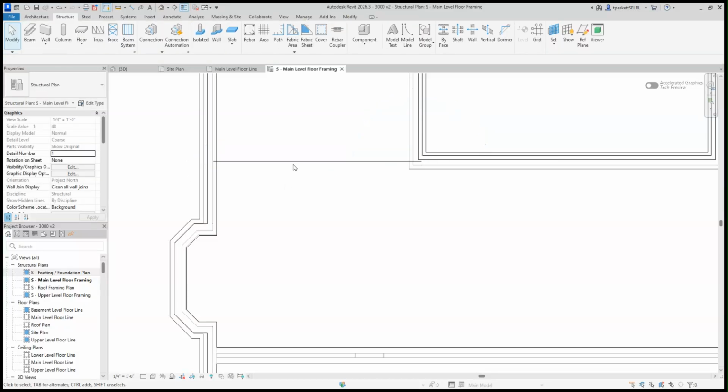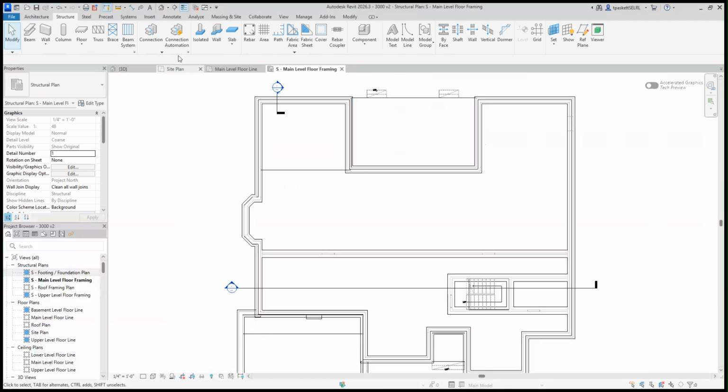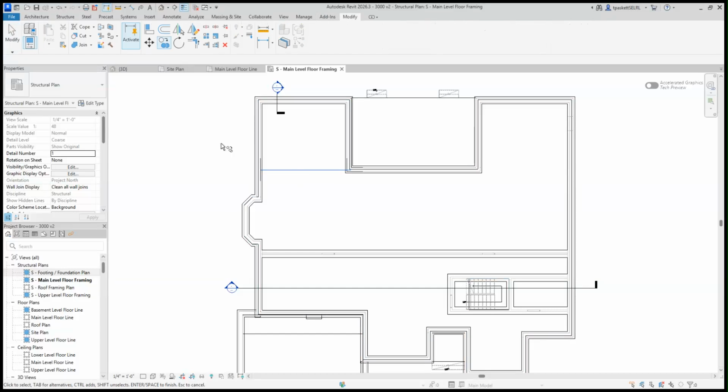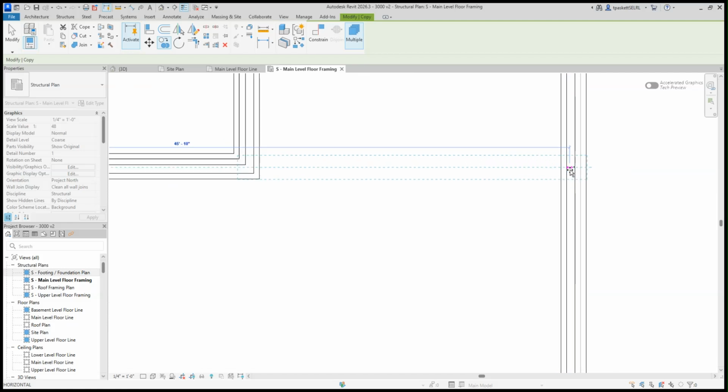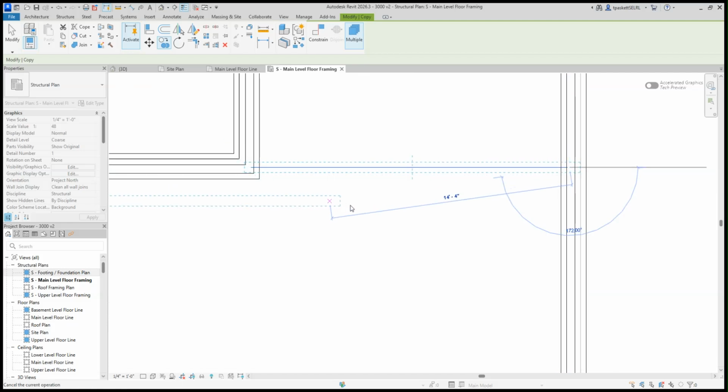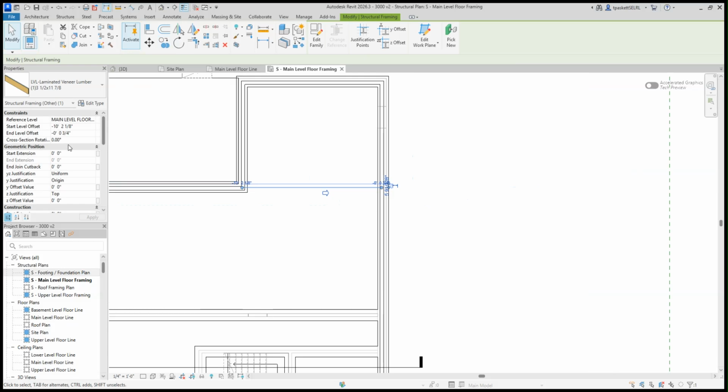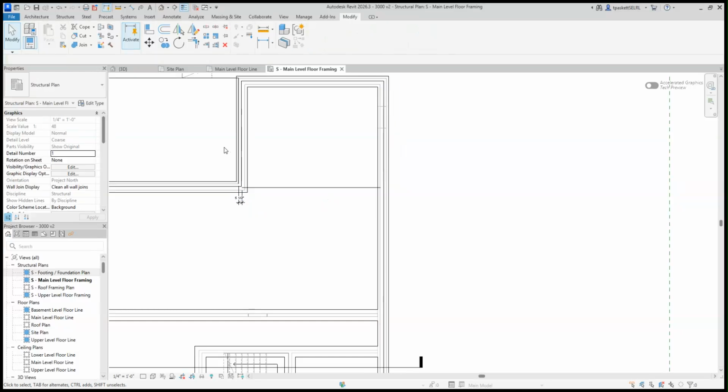Like so. Okay, so now I've got a beam there. I'll have the same beam over here, and I'm just going to use a copy because I don't want to go through all the settings again. If I copy it, finish that, grab that, and just go straight across, I can place it a little bit quicker than rebuilding it and checking the depths. But look, in moving it, it shifted. It's 10 feet down. It's at a slope. So I'm just going to highlight that and Control V and put it back in level. Watch that in these structural things because it does get out of level really quite easily.